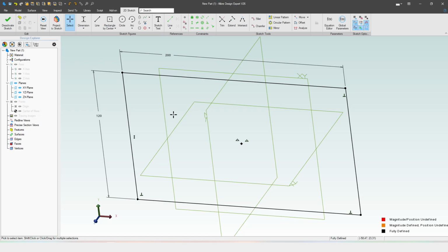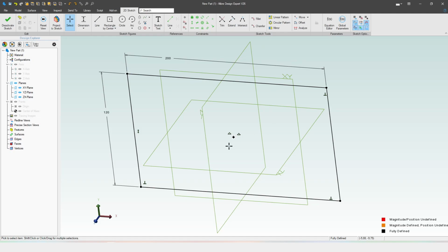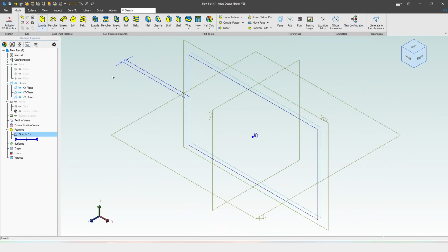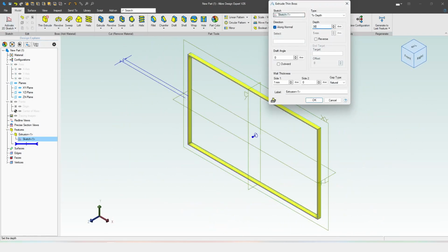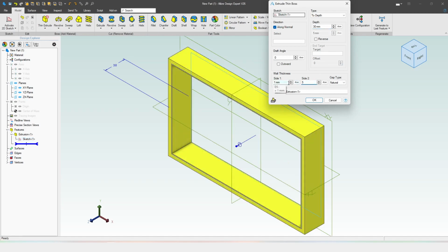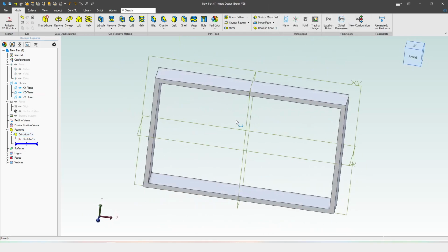First, we'll create a honeycomb structure that adapts, that conforms to an area. In this case, it's a rectangular area, but the principle stands for other shapes, circular, rhombic, whatnot. So we'll have a honeycomb structure in here that will conform to these dimensions. And I want to have a frame that's 30 millimeters tall, and I want to have it 5 millimeters thick only on the outside. So this is our frame.